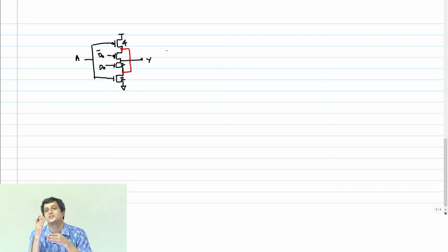Therefore, the two resistances are in parallel for most of the time, and you can slightly give an allowance, and typically they make this also 2. Slight deviation from what we have done because these two NMOS and PMOS are in parallel for both logic states. This is very important because when we do sequential circuits later, we will use this.